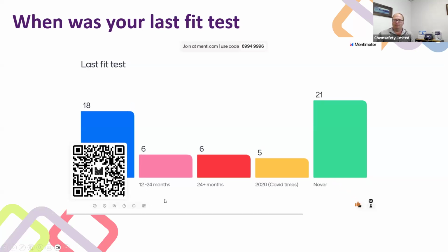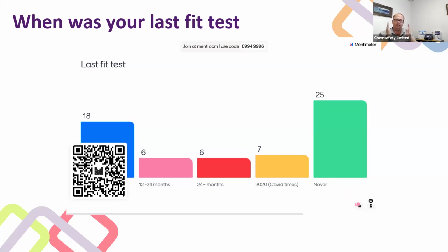So that is awesome. It isn't surprising when we go to sites to do exposure monitoring that we ask, when were you guys fit tested? And they say, the guy showed us when we get in, and we do the positive pressure, negative pressure thing, and that's actually a fit check. So every time you put on a negative pressure respirator, there's a fit check where you cover the inlet valves with your hands and breathe in, and you should get a vacuum feel around your face.